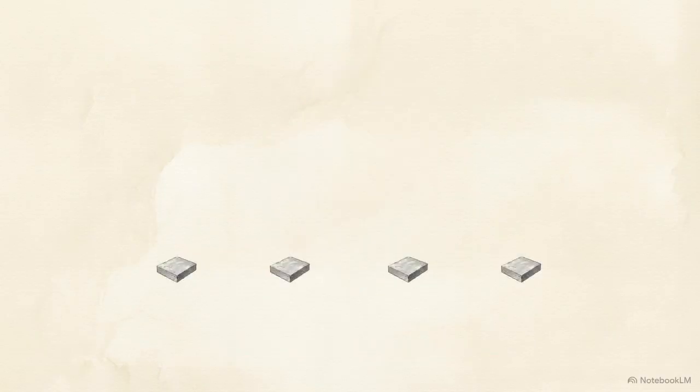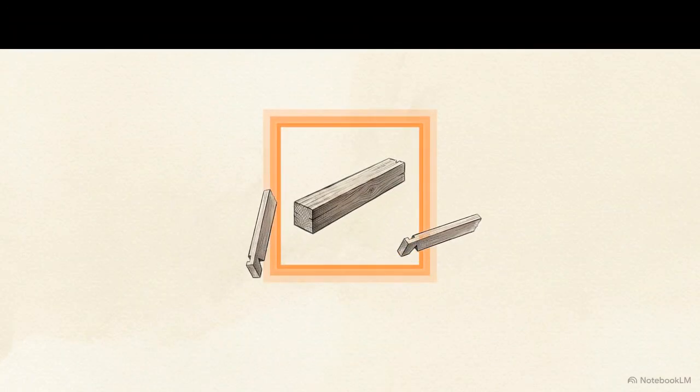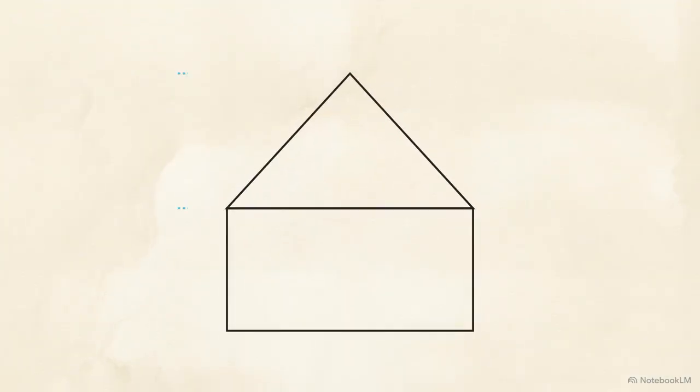We start with bare load-bearing walls. First, we add plates, horizontal wood placed flat along the top to spread weight evenly. Next, the ridge, a single horizontal beam suspended high in the center. The ridge acts as the top connection point. It dictates the highest line of the roof and anchors the top of the angled framework. Between the top ridge and the bottom plates, we have established the boundary points. Every ounce of weight must be successfully transferred from the top down to the base.